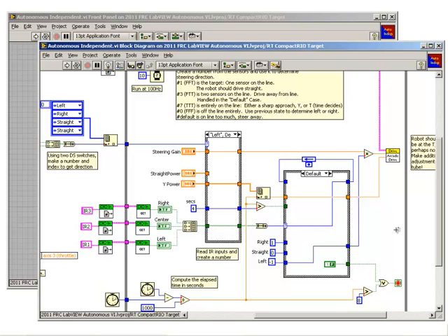We'll begin by looking at the default case. In this case, the Y power is going directly to the Y-axis of the arcade drive function, so the power of the robot will be whatever the Y power was at that second. The value of the current case is wired into a feedback node, which we will discuss in case 7, where the value of the feedback node will be used.